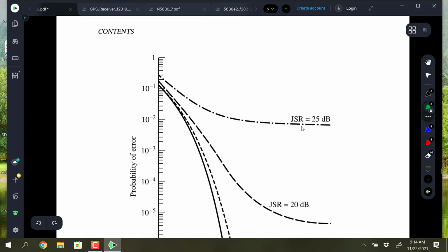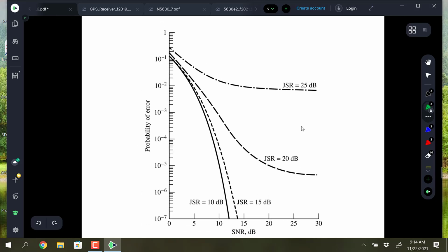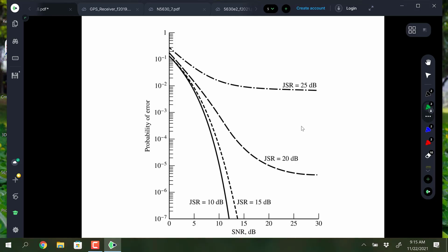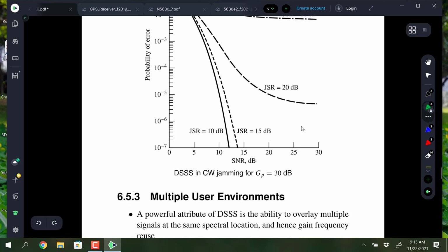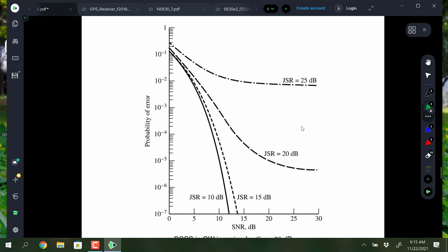So plotting that out is what the book has in it, and this just shows you things that can happen. This is the standard BPSK error probability curve. And this is a processing gain of 30 dB, which would be 10 to the 3 in power ratio, 1,000. 10 log base 10 of 1,000 would be 30 dB. So with that much processing gain, and I said the GPS system is getting around 10,000 on its 50 hertz data.